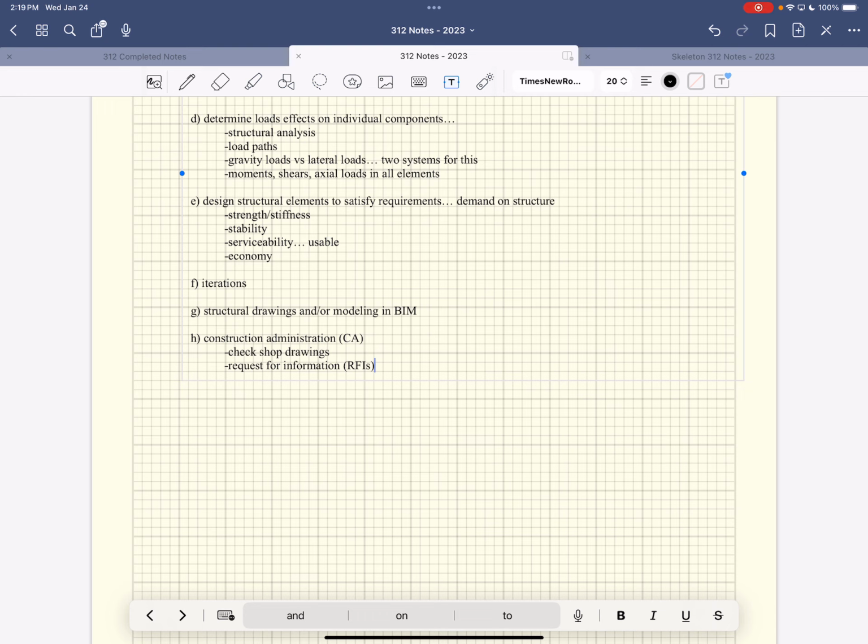If the contractor's doing it right, they will make sure that it's okay with the structural engineer first. Or like, I couldn't find that size of beam, I can only find this other size of beam, it's a little bit bigger, is that okay if I use that? Or it's a little bit smaller, is it okay? That's called request for information. The contractor submits them to the structural engineer, they double check it, and then they respond to that request for information, either yes or no, or sometimes it involves additional tasks of calculating things.